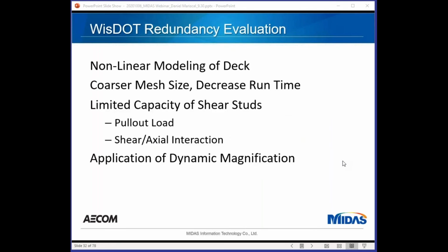For the redundancy analysis, originally we had thought of using brick elements for the deck, but since you have to divide them in the thickness of the deck in maybe 1 inch increments, and then you have to divide it longitudinally, it was going to be a very big model, and the runtime was going to be tremendously high.